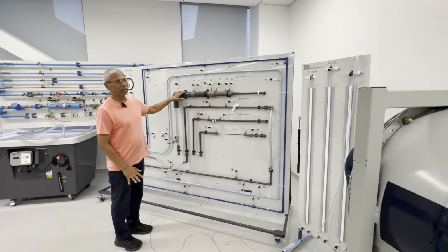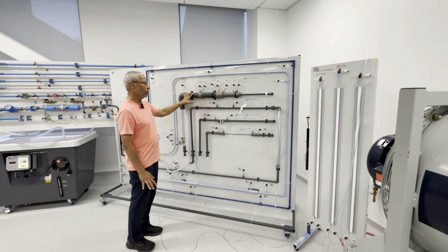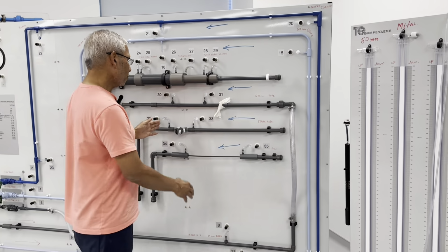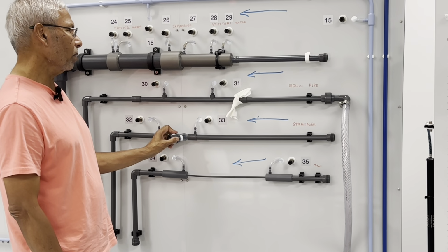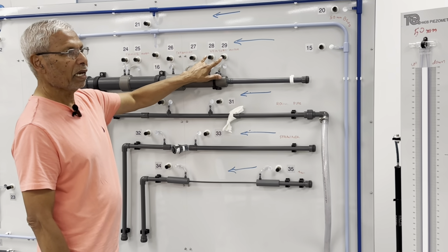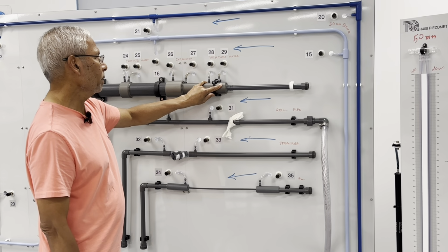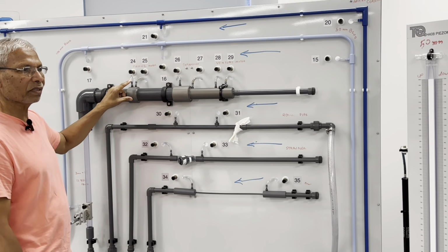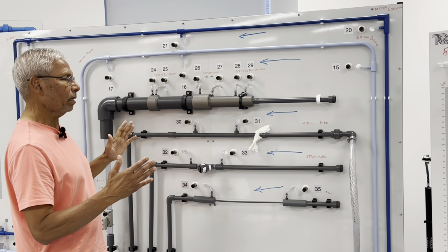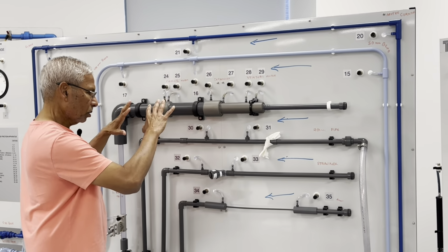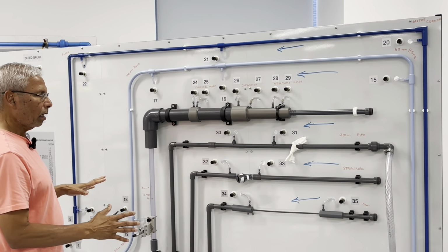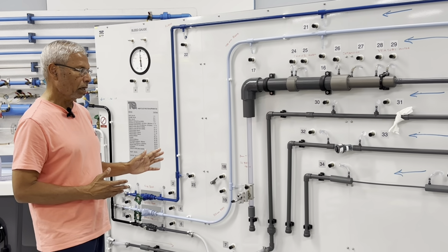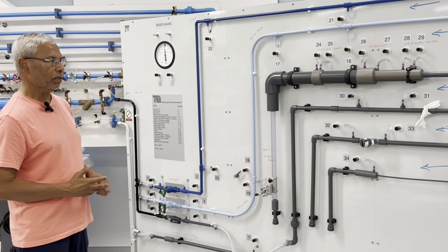There are a lot of things you can test with this equipment. For example, if you want to do the sudden expansion and contraction, we'll talk about it in a minute. Or if you want to see in a strainer how much restriction is taking place, or in a venturimeter, how it behaves and how the expansion takes place, or if you're going through an orifice, what the pressure head differential would be. So like I said, it has multiple things you can check, and it's a very universal apparatus.